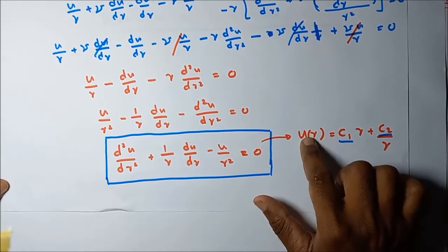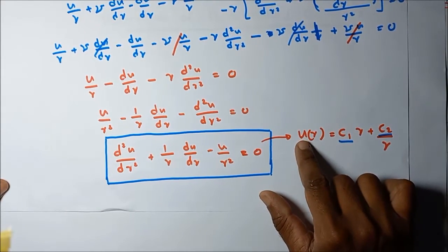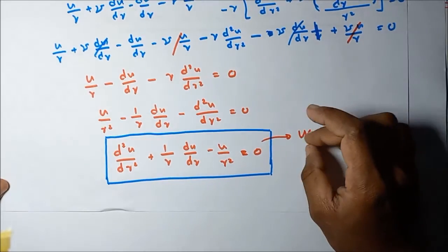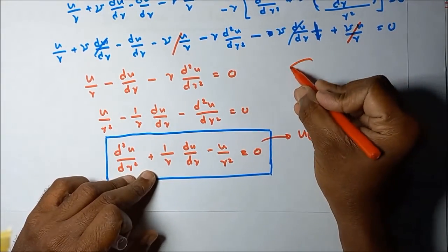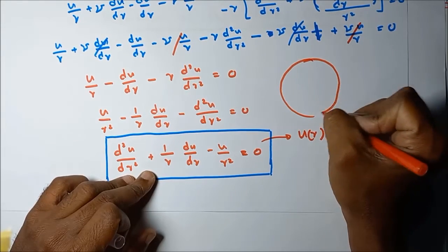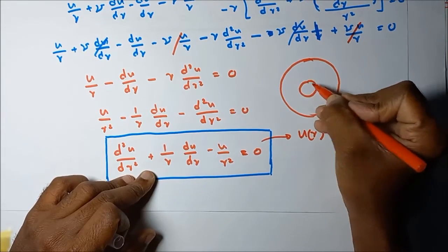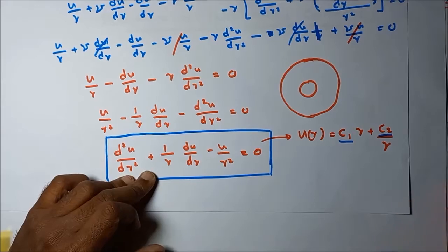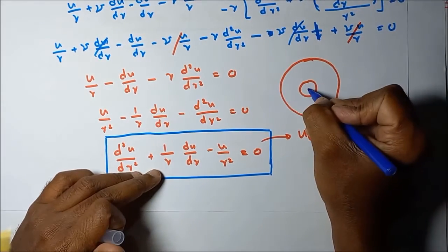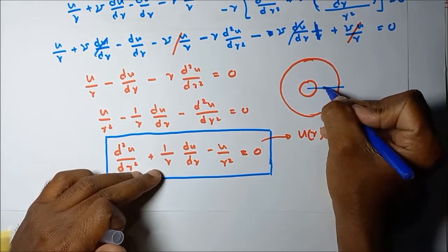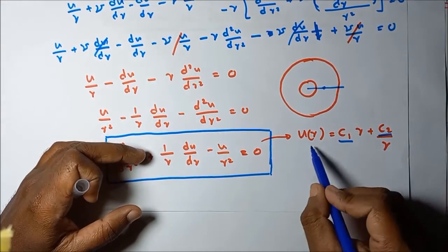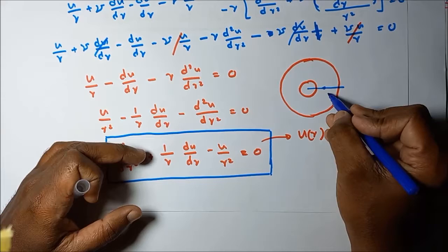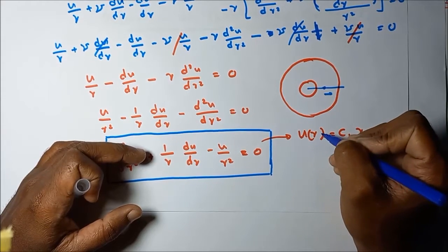By substituting the displacement function, this is how the radial points are displaced when the cylinder is subjected to internal and external pressure. That means how a certain point displaces in the radial direction is expressed using this u r function.